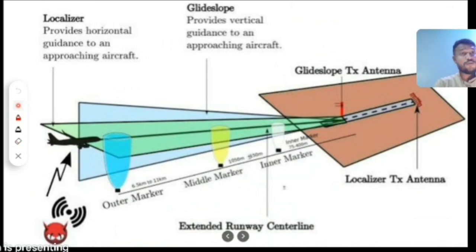So how are they providing the indication? Suppose your aircraft is flying above the outer marker. You will get a dash sound, and in the cockpit you will have OM written on the PFD. You will not get any measured distance indication.